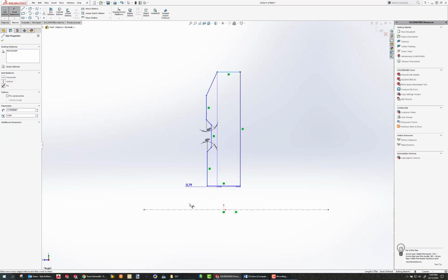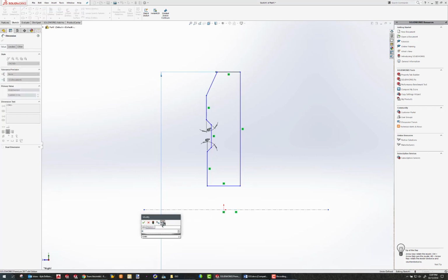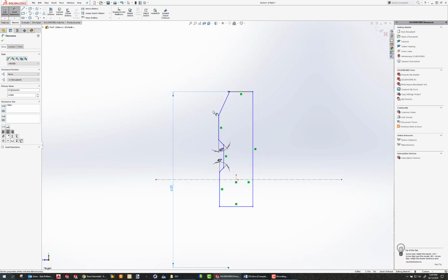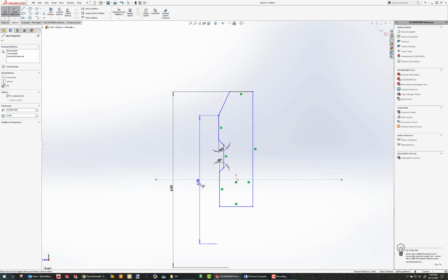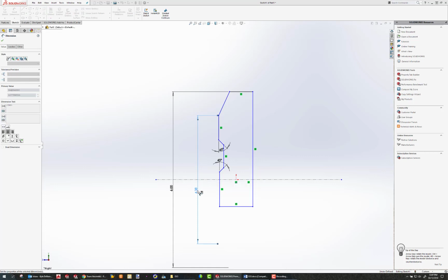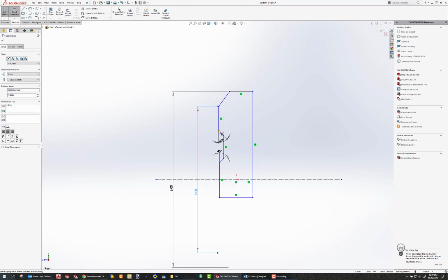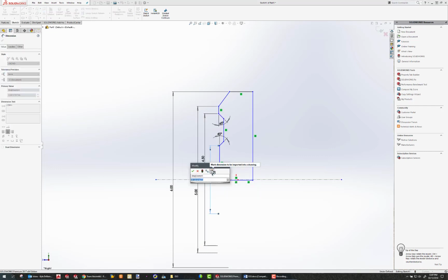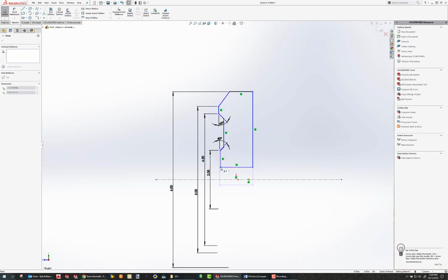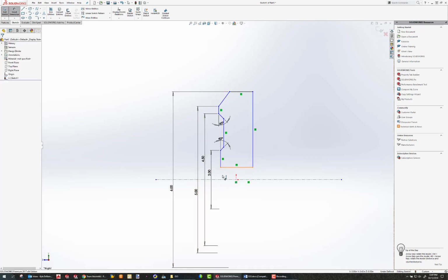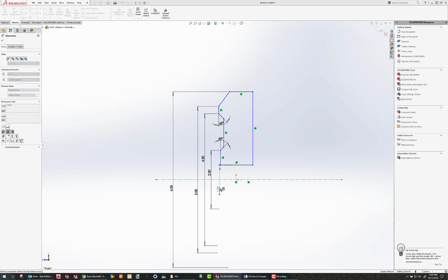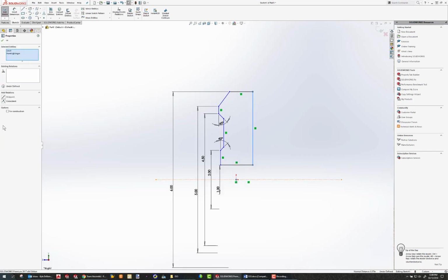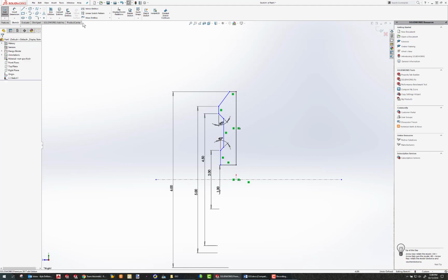Remember, if I'm doing a revolve, I can click between a solid line and a center line, and if I drag my mouse below the center line it doubles and I can input the diameter directly, which is 6. Which is a pretty neat tool when you're using revolves. So type in my diameters here. This line I'm going to drag above so that I can go like this, and this is a 1. I'm going to make this line and my origin coincident to make that fully defined.